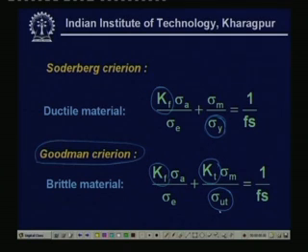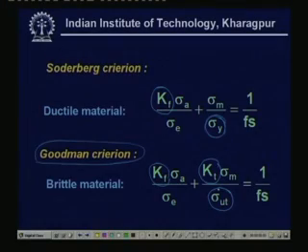The reason is that this theoretical stress concentration factor, as we have seen earlier, is a very localized phenomenon, and in the case of the ductile material, even if it is under a higher stress, it gets locally stress relieved and does not affect the material to the extent that it affects the brittle material.